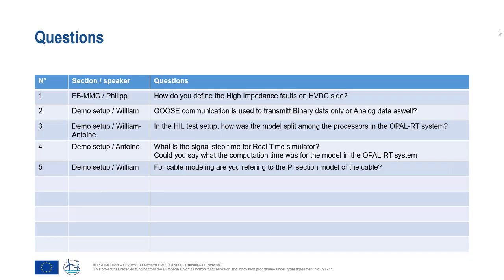But in case there is a high impedance fault, the overall discharge process through that fault takes longer because there is more resistance in the fault current path, and so the converters have to work more to actively discharge the DC network. Especially during high impedance faults, you can really see the difference between active discharge of the grid and passive discharge, for example if you block the converters.